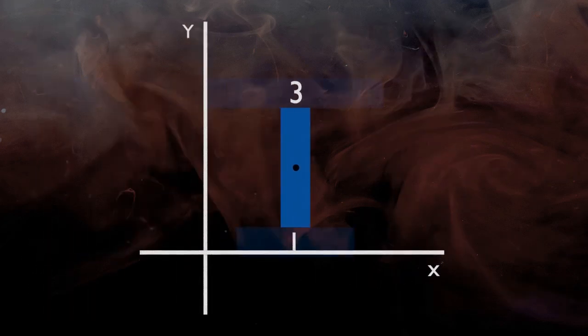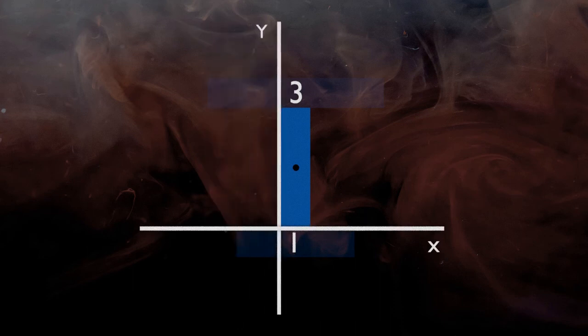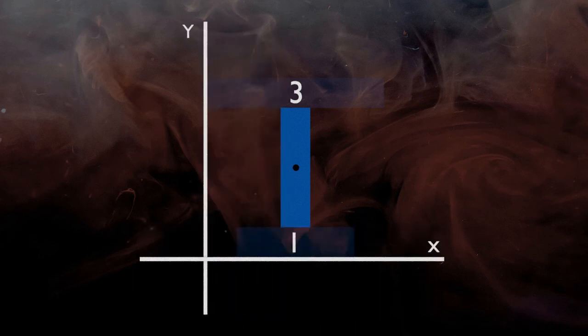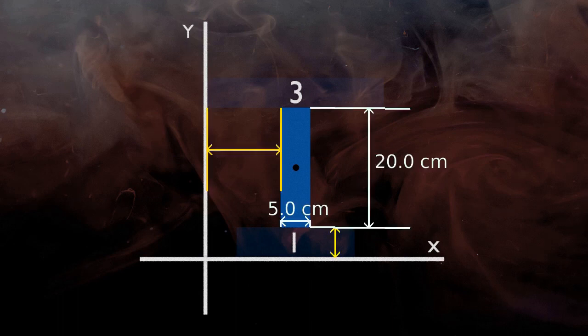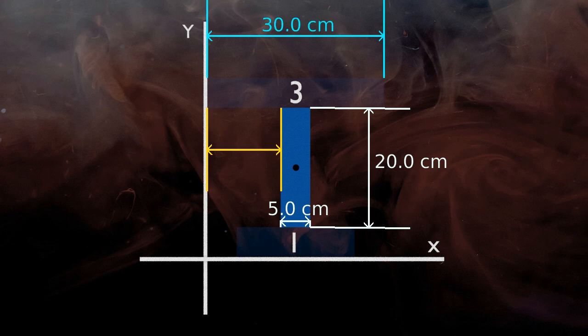Again, these individual coordinates of the rectangle are for this location of the x and y axis, but the reference axes are some distance away from rectangle 2. So we have to add these extra distances to the previously found coordinates of the shape. Again, the distance from the y-axis we can find out using the dimension of the top flange.